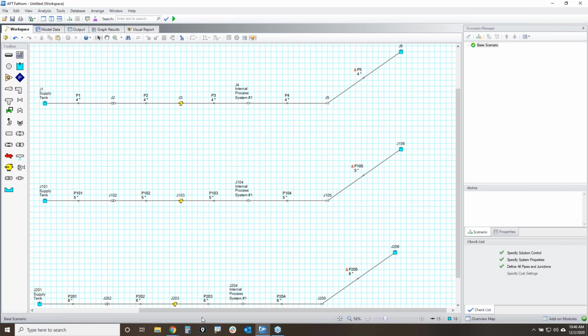All right. Now, the next thing is to set up my tank sizing. So again, the liquid surface elevation I specified for my tank of 10 feet is just a flat out guess. So I want to make sure that I have plenty of NPSH available for my pumps. But the thing is, I don't have a pump curve or an NPSH reference value. So I'm going to keep it a little bit more simplified. I want to make sure that every pump has a minimum of 5 psig in suction pressure at the pumps. So the way I'm going to do that is by changing the supply tank liquid height in order to ensure that I have 5 psig at the pump suction.